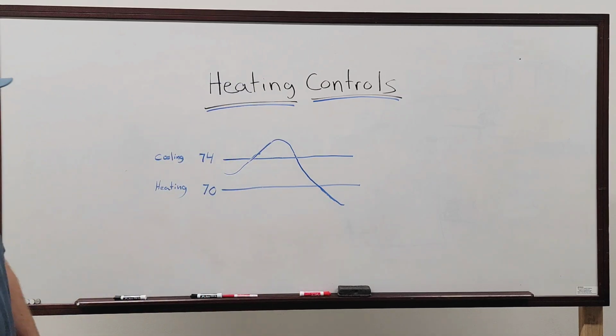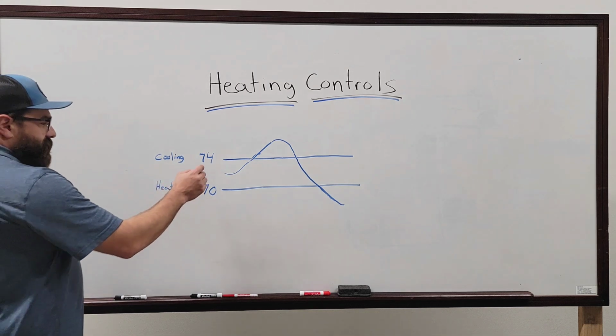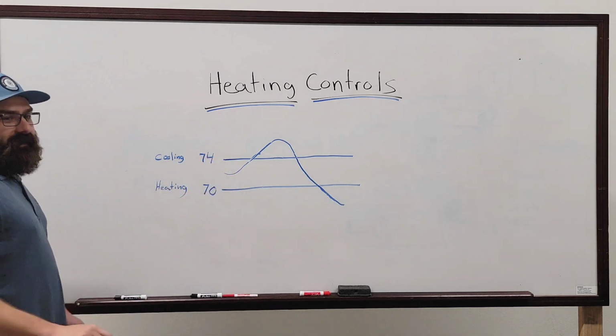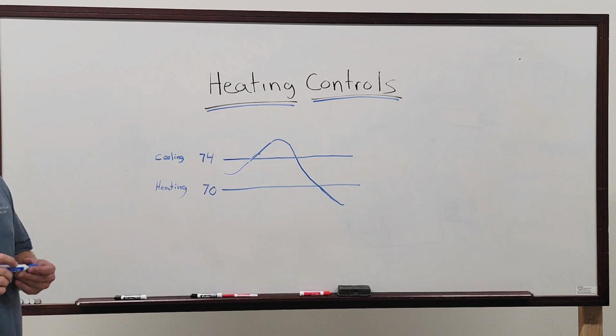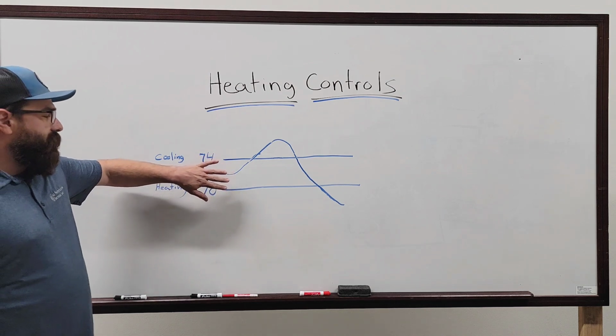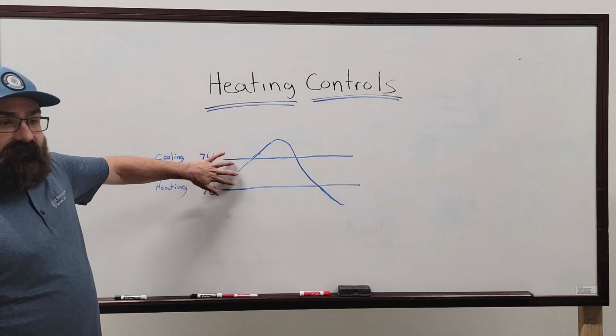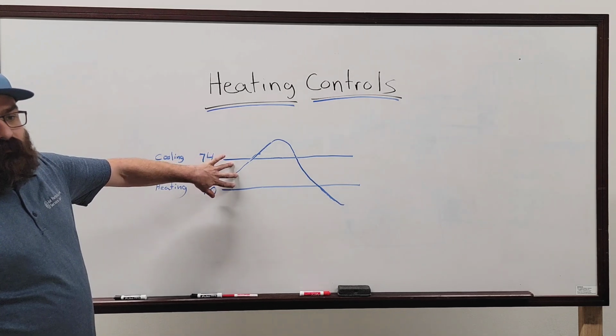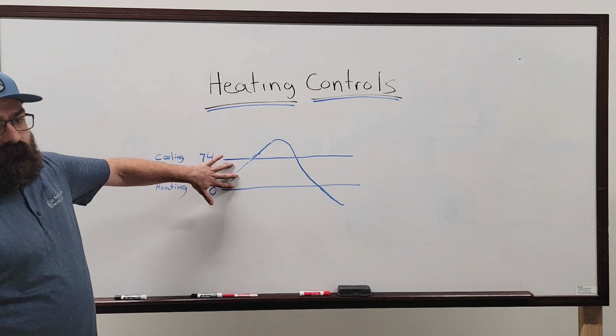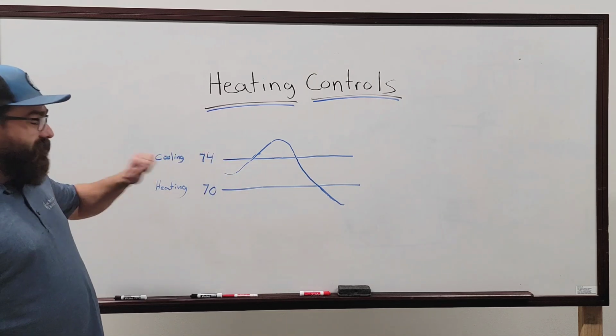Kind of makes sense. The main thing I wanted to focus on was just because it's in the middle of those, don't expect it to be one or the other. We fight with that a lot. And some boxes will, even if it's, so parallel boxes, we deal with this a lot. They could be running the fan in this section, right? So it's satisfied, but it's in heat mode and the fan's running.